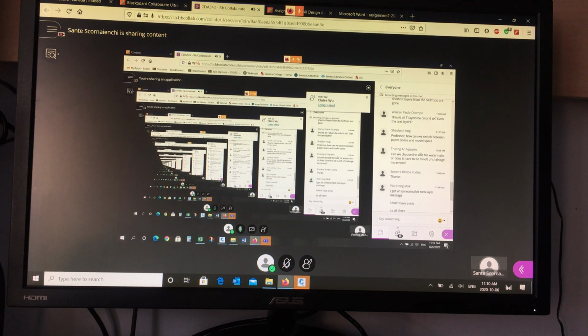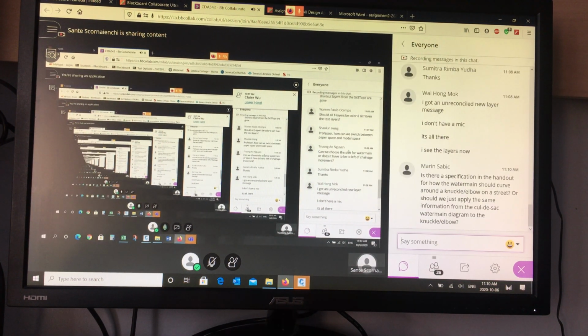I want you to see the service layers, right? Because they're going to be the sanitary, storm, and water. If you leave them in color, you'll at least be able to see that they're dashed. So the line type will take care of the fact that they're existing as opposed to the color. Because we have solid lines for sanitary and storm.